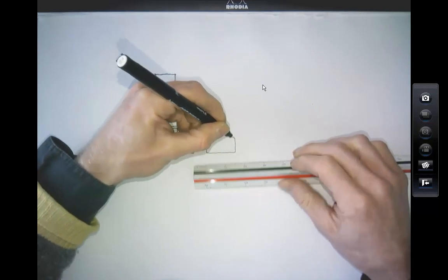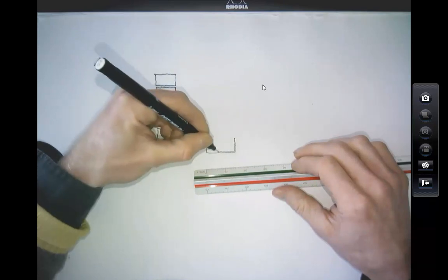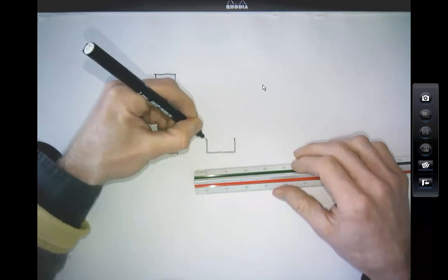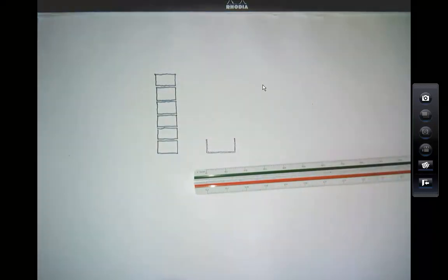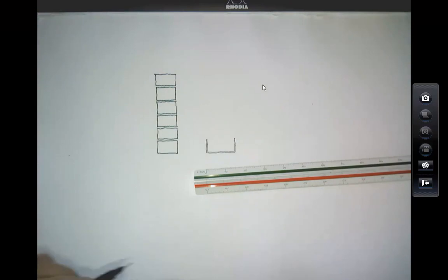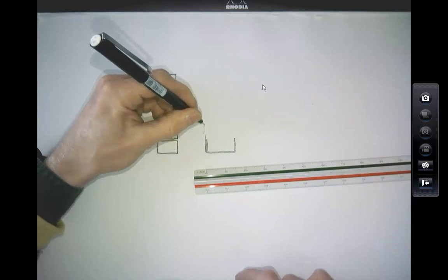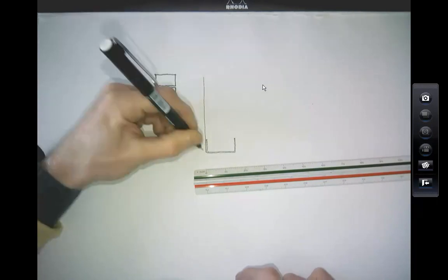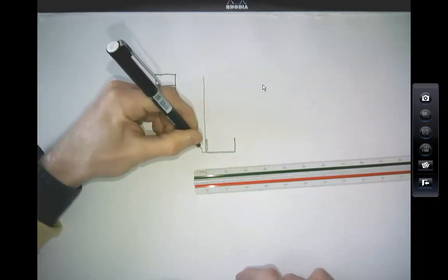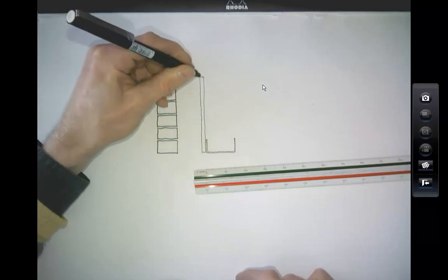Now, these lightweight steel frames will be designed by a specialist, so you don't need to worry too much about that. It's just lightweight bits of pressed steel, and they can screw it all together on site. I've got some pictures of that. And so we fix to that on the cavity side our CP board, which is what I've just passed around there.